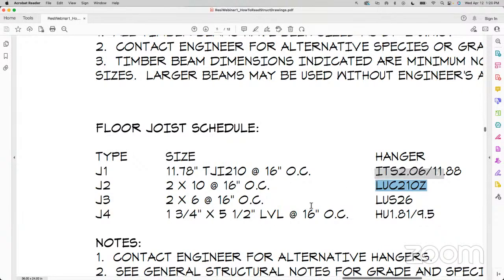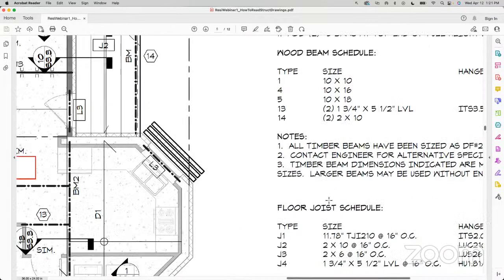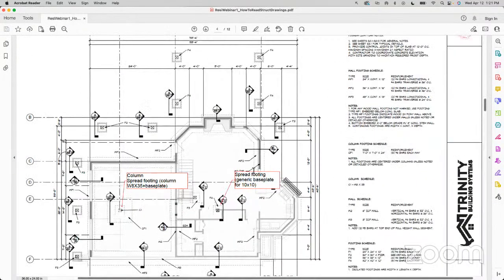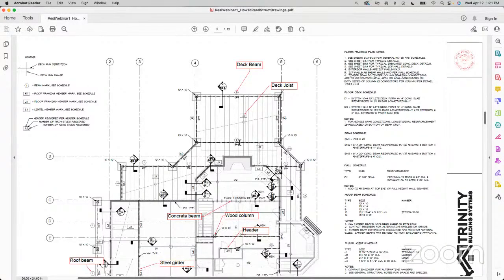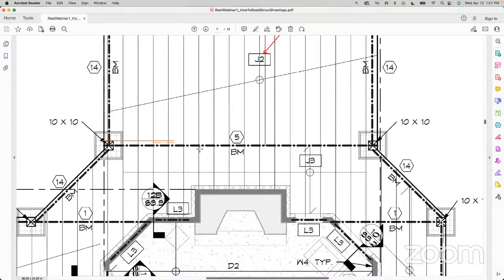Now, for the sake of highlighting the wood connections calculator and showing you another way we can determine this bearing length, what I'm going to assume is that, let me scroll out here, this beam at the bottom, or the connection between our joist and this beam at the bottom, is our joist on the hanger, actually. So we're going to assume at the bottom, it's not bearing on top, but it's going into the hanger.